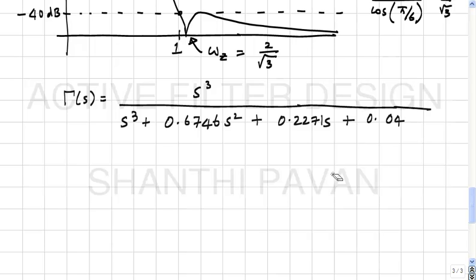The reason is that it can be shown that this whole process of generating the network from the reflection coefficient is a very sensitive process to the numbers here, and therefore it's mathematically what is called an ill-conditioned problem, which means that you can't simply truncate these numbers after the first decimal place and hope that things will be okay.